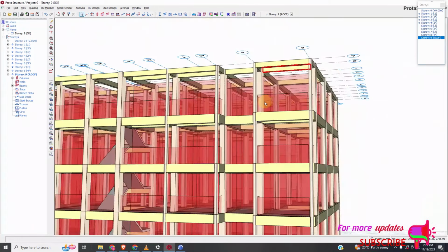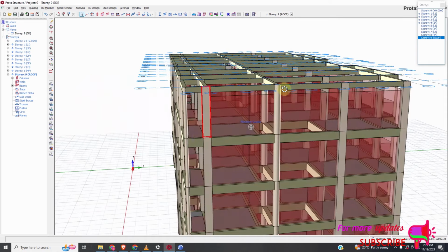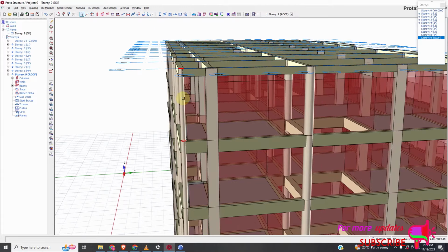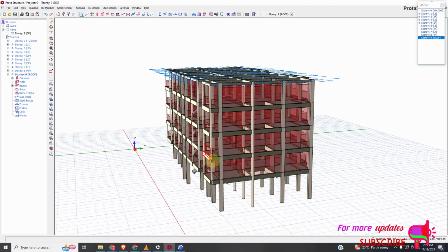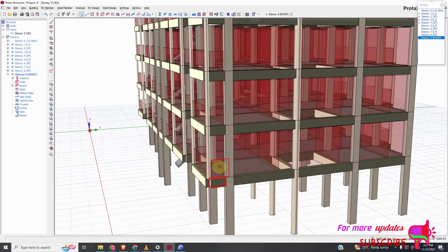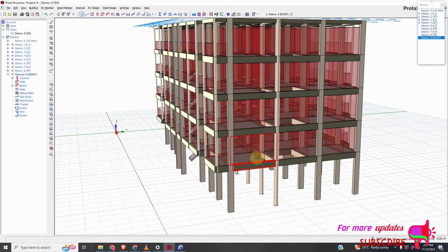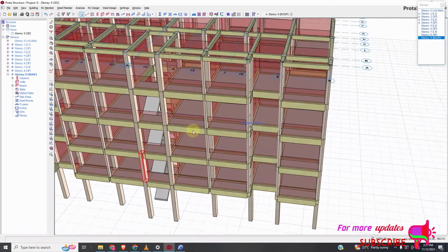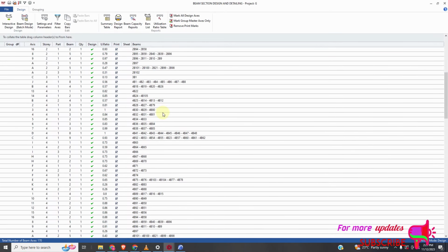Maybe perhaps for these columns here, you can see these columns in between the balconies. Maybe when we use 12, maybe, but for columns we should use at least T16. So let's check the beam design. RC beams, story beams. All of them are passed.